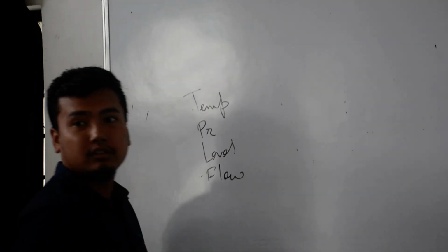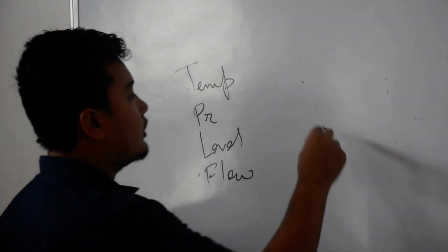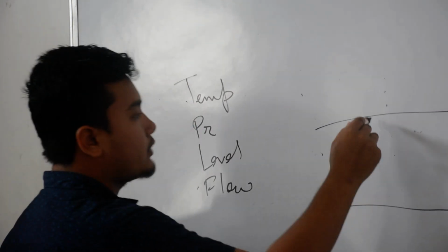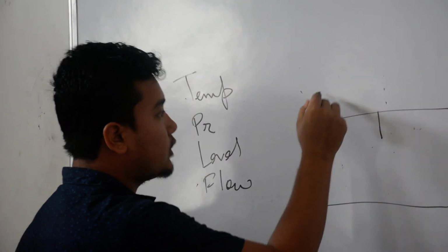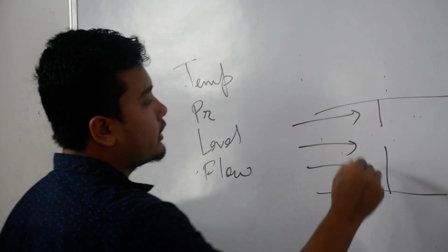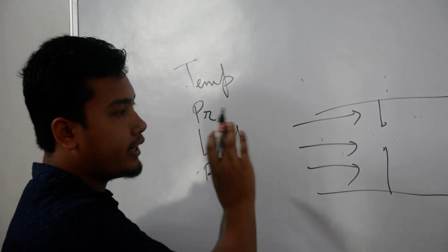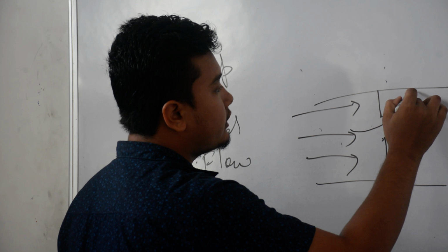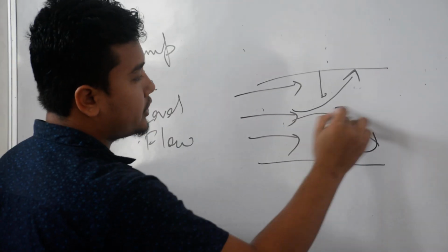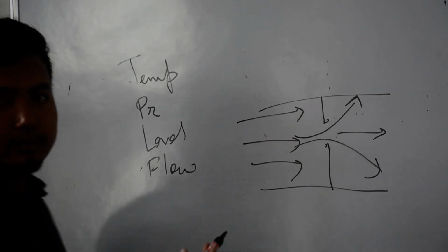How can you measure the flow? Sir, to measure flow in a pipe, we will give some orifice plate. In case of liquid, orifice plate. So when liquid flows through here, since there is only a small space here, the water will strike at very high speed, and it will strike the nearby wall in some position like this. So now with the help of a differential pressure transmitter,